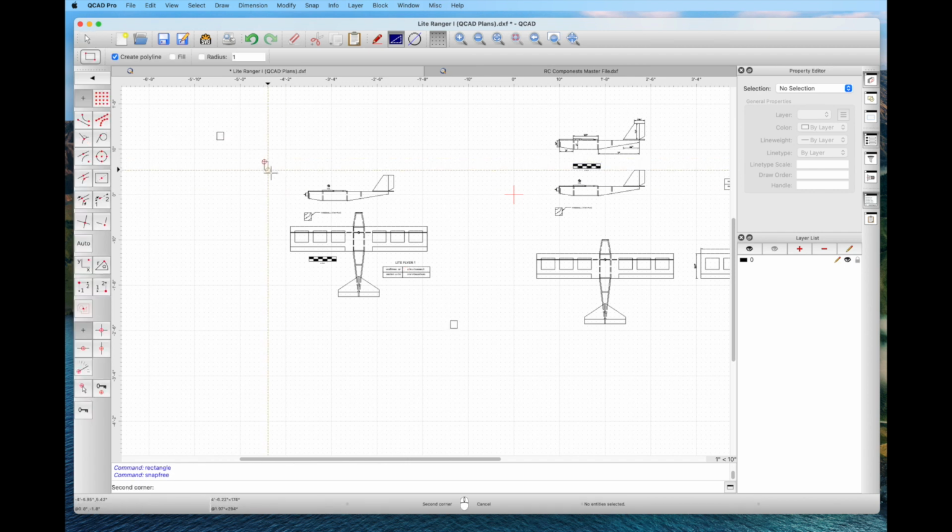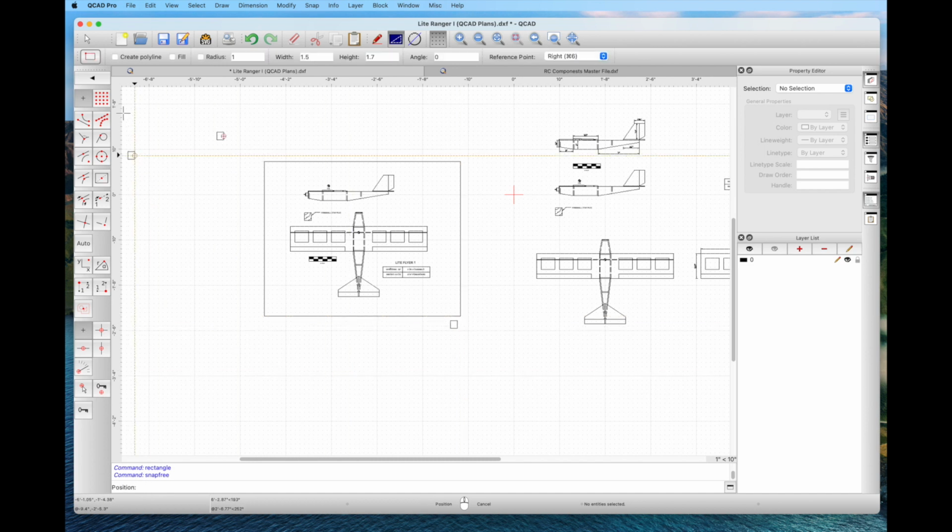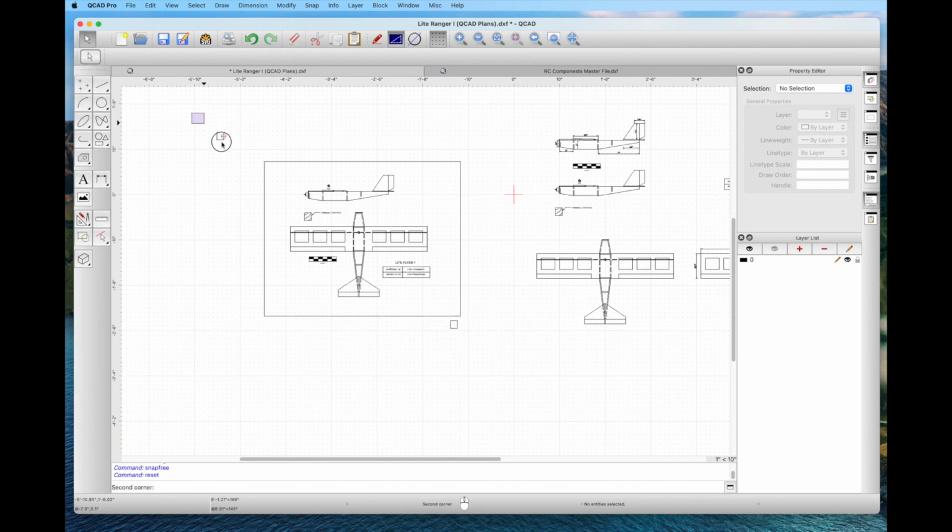Then we can use the box tool again to draw a box around this plan. We use the parallel tool one more time to make it a double-edged box. I think that makes it look a little bit better, and that's what we do to make it a little bit more presentable. I just pick a 1/4 inch in for the border of the box.